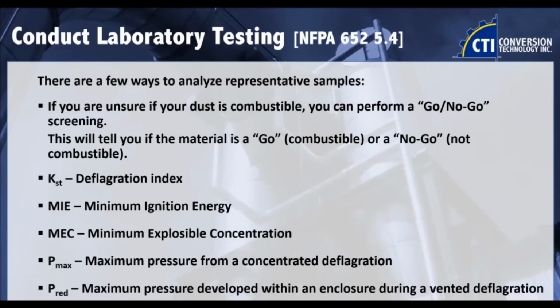And then for further testing, you would do the MIE, or minimum ignition energy, which matters if you have a big static problem in your equipment, or dust moving through a duct or conduit, where you get static buildup. You need to know how much energy it takes for that dust to ignite. So that would be really big with your bonding, grounding, and electrical maintenance. And then the minimum explosive concentration, as we discussed earlier, of, well, how dense does that dust cloud have to be?